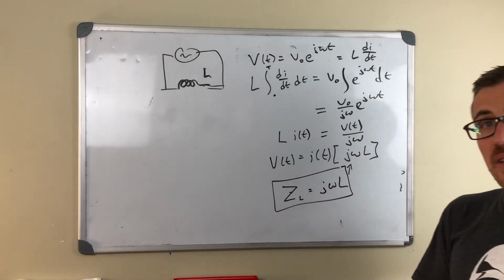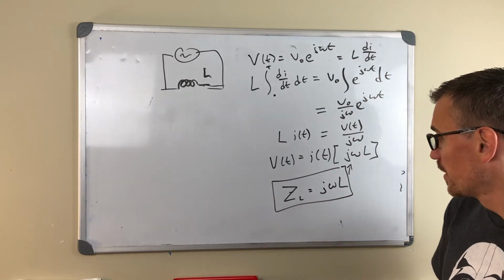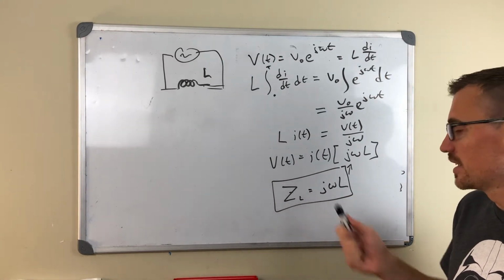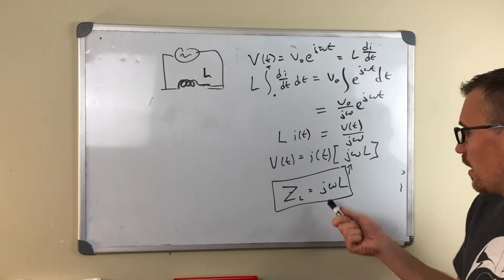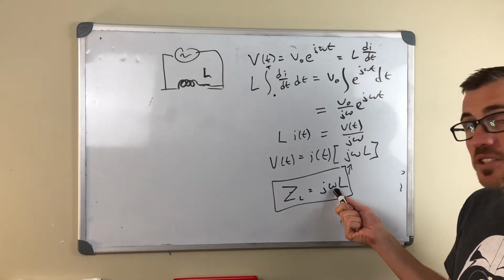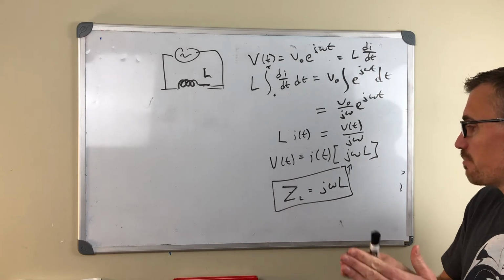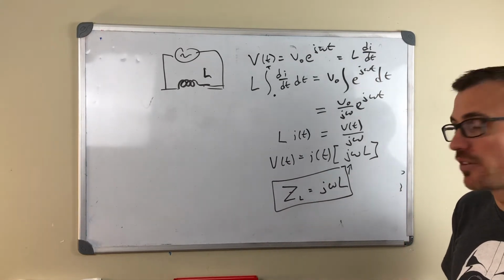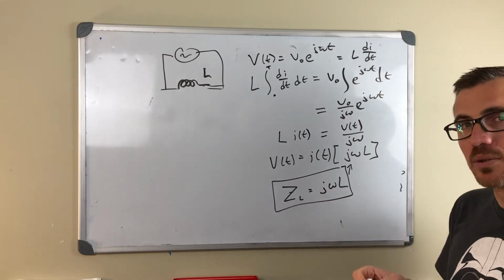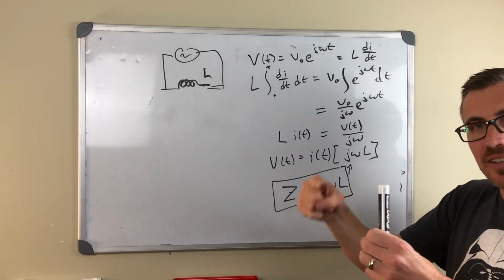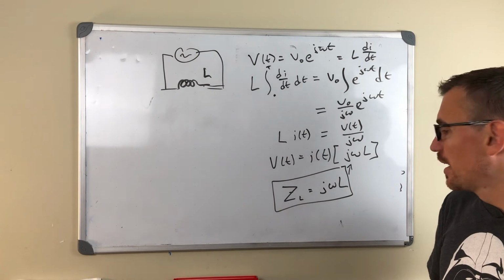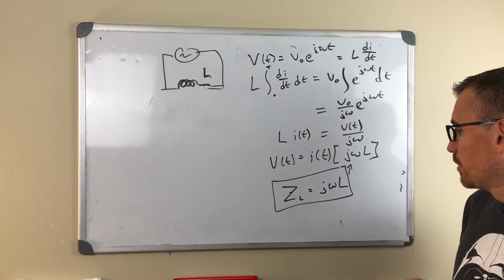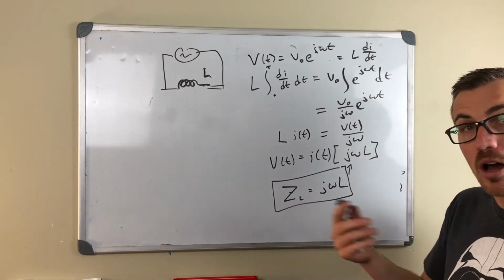Again, there's a phase shift there. There's a phase shift of 90 degrees. It's now positive instead of negative. And conversely, with higher frequencies, we get more impedance. The magnitude of this gets higher and higher. We're going to get less current flowing. For very low frequencies, basically there's no inductance. It just behaves like a wire, and it's going to basically drop no voltage.